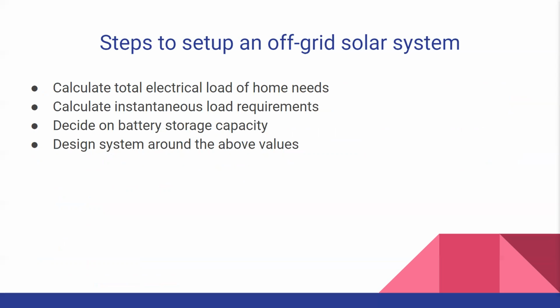For the setup of our off-grid solar system, you need to establish a few steps. First would be to calculate the total electrical load of the home and its requirements. In addition, we also need to find the instantaneous load requirements. Our battery storage will depend on the load of the home, and our system will revolve around these values that we determined throughout the report.